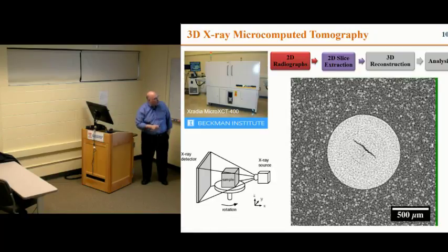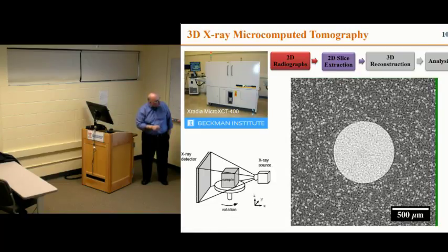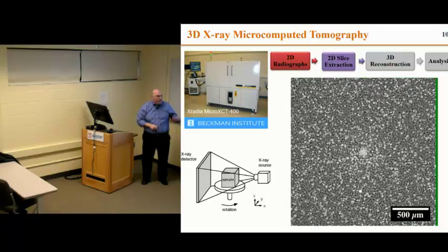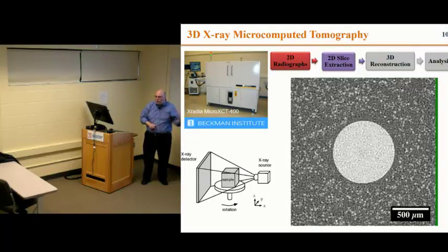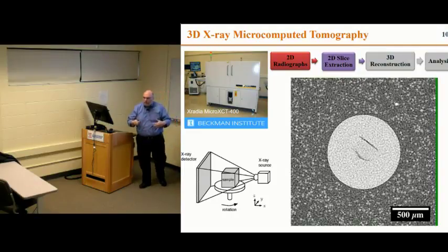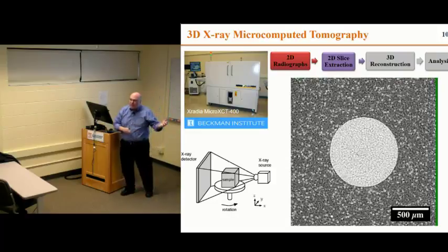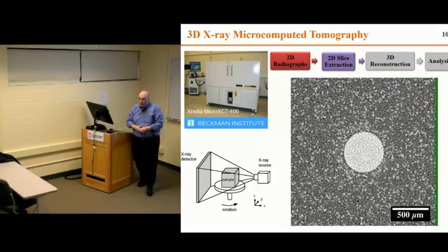So this is essentially the alumina sphere. This is the matrix, and you see all these little white dots in here. We have placed these white dots, and these are the ones that will take the role of the surface speckle pattern of paint that I showed you a little while earlier for the 2D image correlation, right?